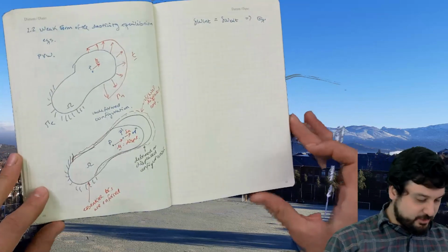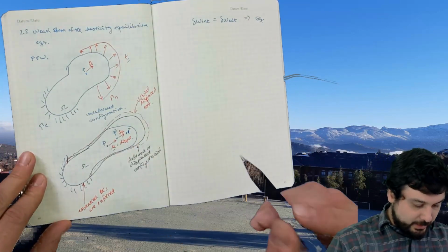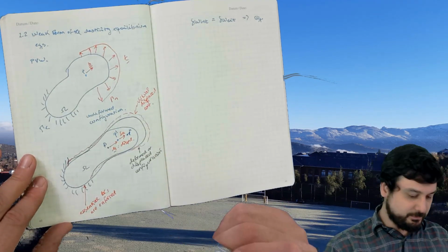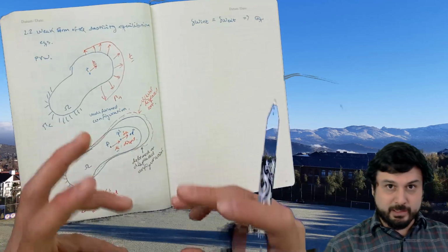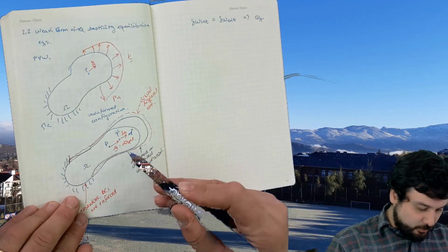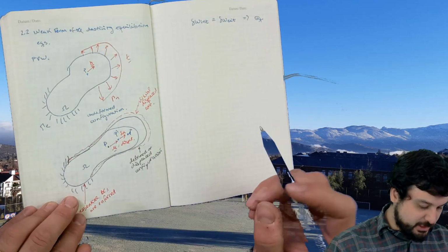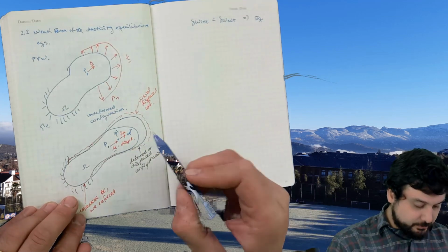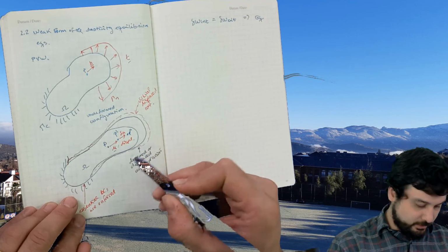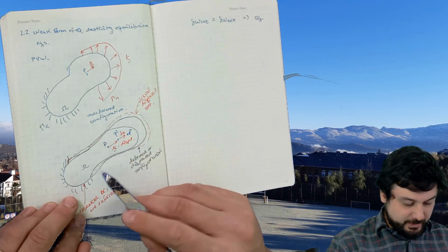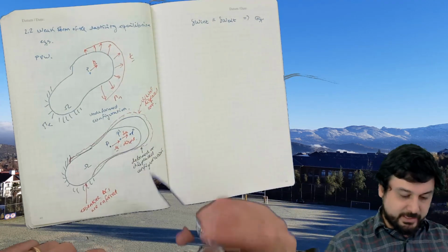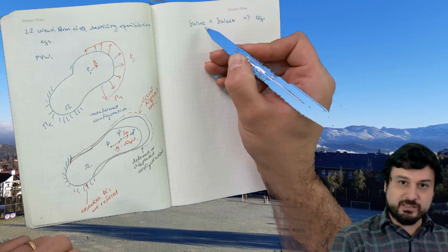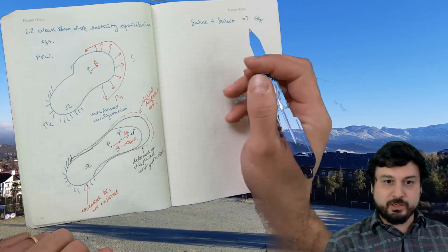In the case of virtual work, you have the following statement of equilibrium. You say, okay, U is going to be a solution of this problem. That is, the system is going to be in equilibrium with that black line, that's the displaced configuration. If the system is in equilibrium, then if I jiggle the deformed shape a little bit, if I displace it a little bit more by this delta, and then with that displacement I compute the work done by the internal stresses, those must equal the work done by the external forces.